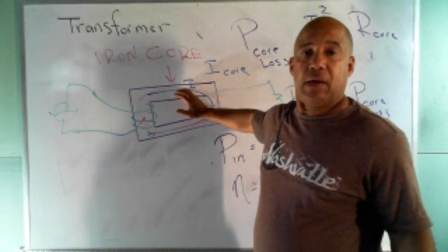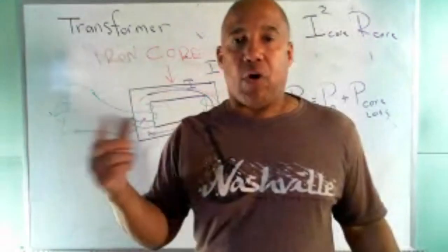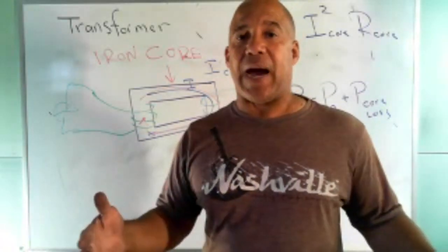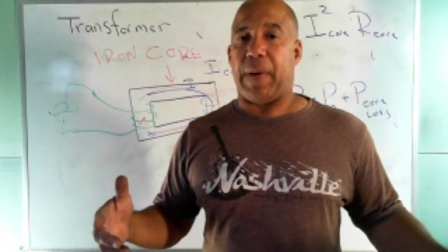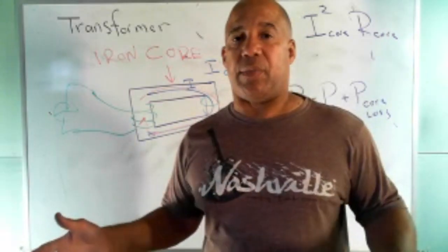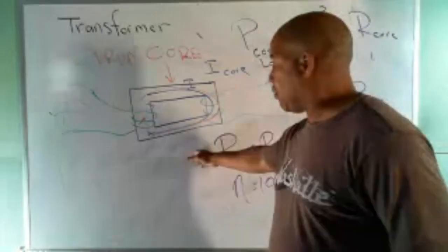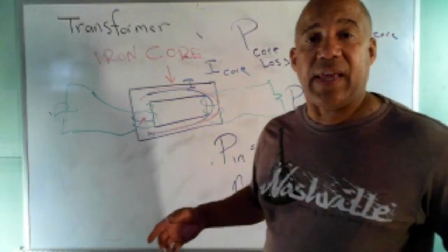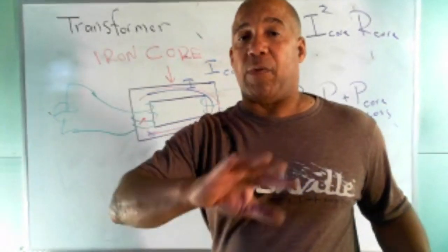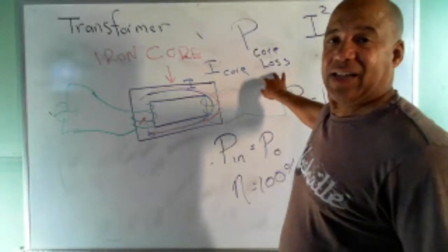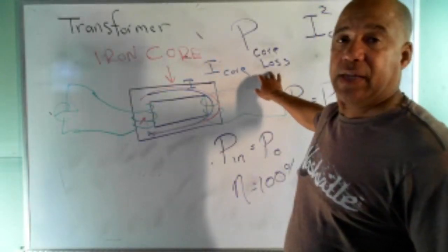Well, remember, a coil is just an inductor, so inductors can't dissipate power. You know, from when we talked about AC power, inductors can't dissipate power. They take energy and they return it to the system. But remember that inductors are made of wire, and that wire, by that equation I just erased, has resistance. And so the heat that you feel when you put your hand on your cell phone charger is the coil resistance. It's like a core loss. You actually feel that core loss as heat.